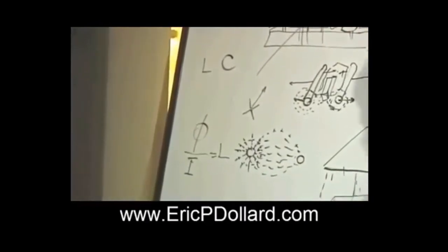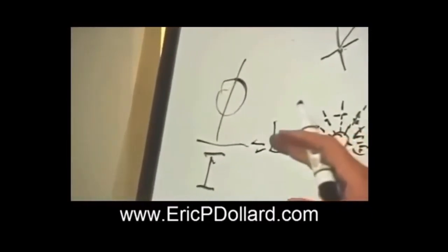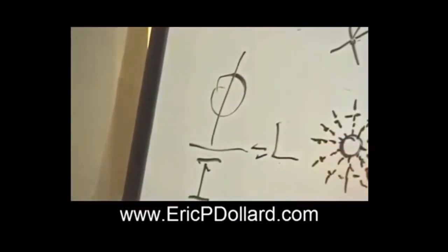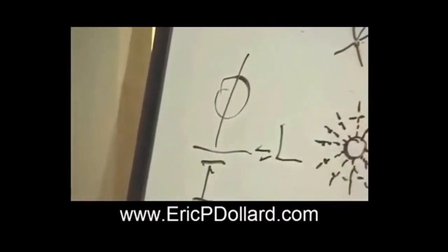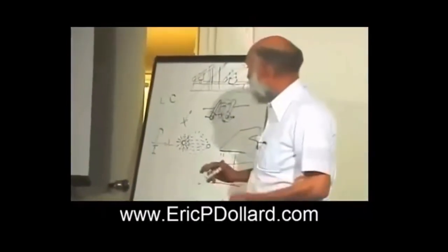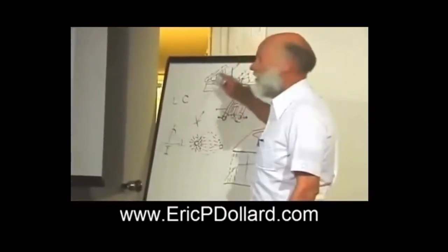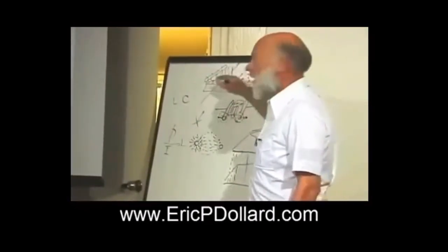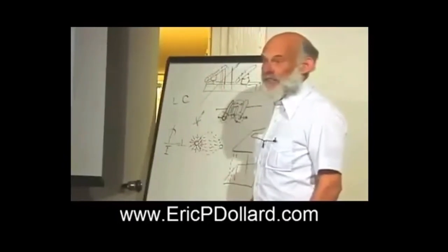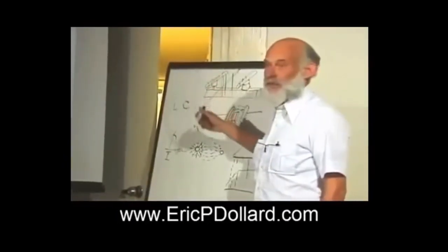This is one of the most important quantities in electrical engineering. There's 4 of these. This is what I'm going to try to develop. L is the ability of this geometry to store magnetism. If I pack that space with iron, L is going to go up because I'll have more magnetism per the amount of current that I can detect by its movement against the wires. So basically the geometry of the wires determines this energy storage coefficient.